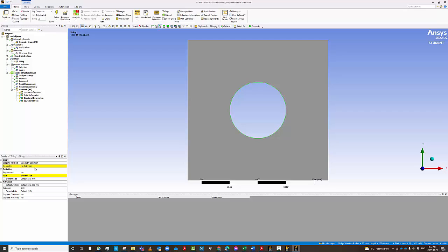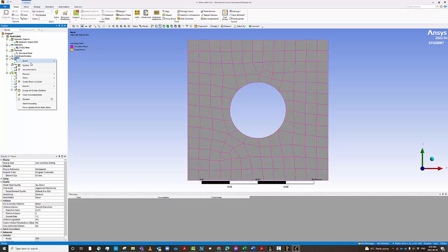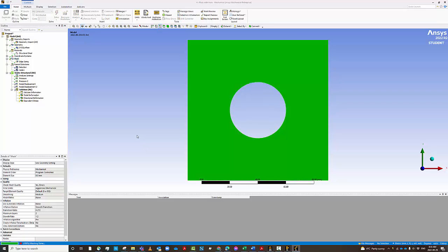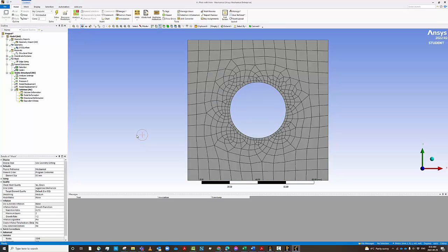In this edge, of course, you can select the geometry and apply. You see here the mesh. Okay, I want to change it a little bit. So element size, instead of 8, I'm going to make it 2, for example, or 3, right? And of course, when you make any changes to the mesh, a lot of problems are going to happen. The first problem is you have to remesh, update. So this is my new mesh.